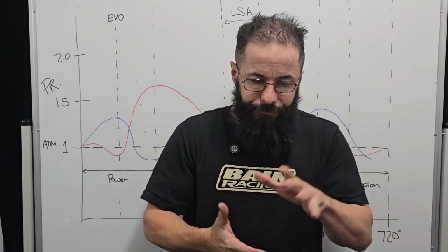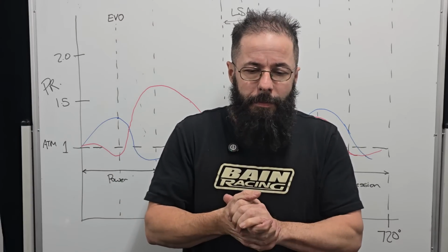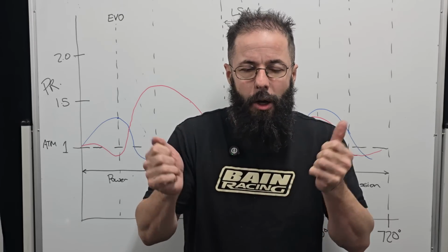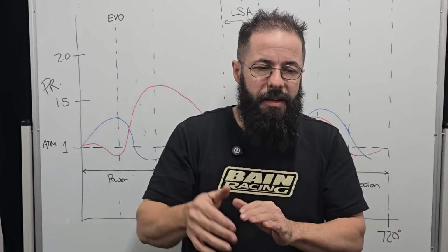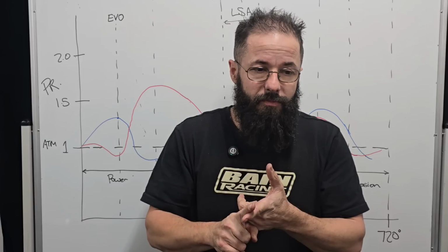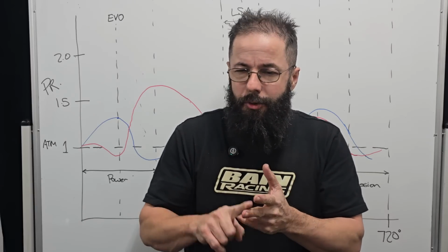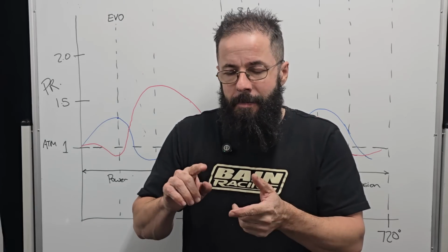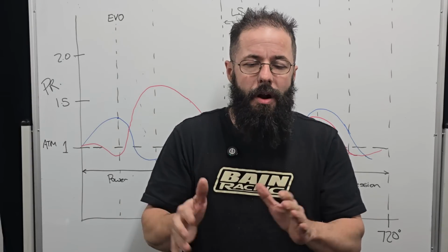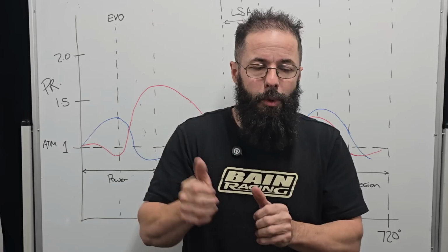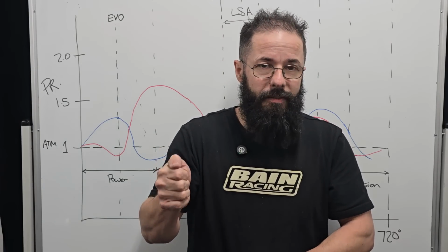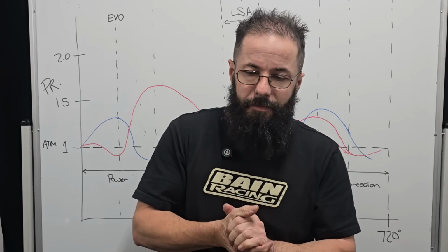Iron headed, pump fuel big block, flat tappet camshaft, cast iron heads that I'd tickled, nothing crazy, just a bowl job. Victor Jr. 850 or 950, something around there. And as I said, 1025 to 1256, 580 lift, 260 on the exhaust on 110, nothing crazy. And yeah, first pull on Sid's dyno after we got a few things sorted out, ended up at 627. So it made a horsepower more than we did on the simulator.